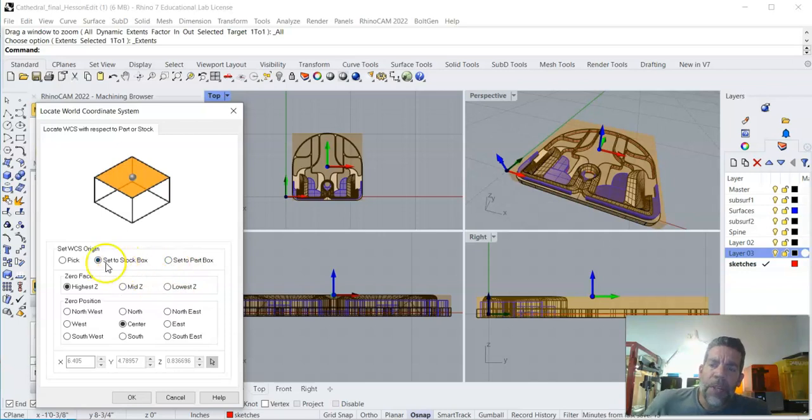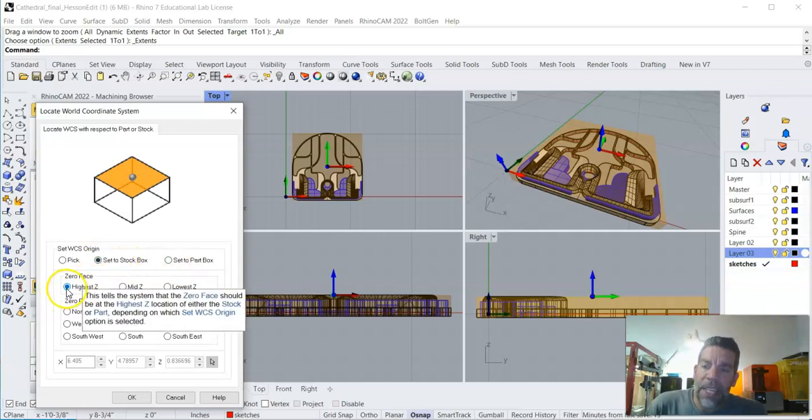Now, a couple things to mention on this. If I put highest Z, I'll be setting my end mill to my stock. Some ShopBot users will set their 0 to their table instead. I think this just varies on what I'm cutting. Sometimes I will set my 0 to the table. If I'm going to be milling something fully 3D and I'm losing my original stock as I mill it away, that's the only time I usually 0 to the table.